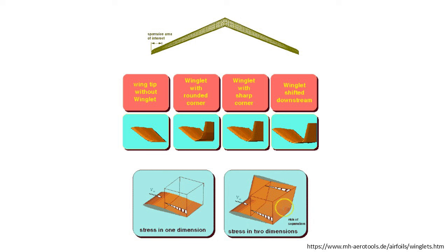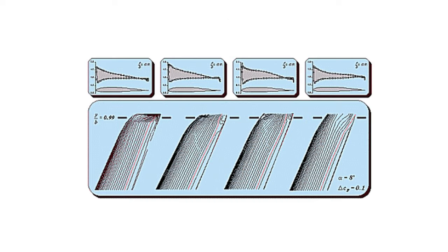Knowing this, you can see how a winglet, specifically a winglet with a sharp transition to the wing, could be an issue. Usually the wing airfoil only feels the pressure rise on the suction side in just one dimension, but with an effective winglet, another new spanwise pressure rise gets added to this in the winglet corner. The boundary layer pressure field in the region will have to overcome the sum of these 2 pressure rises, which naturally gives a higher risk of boundary layer separation. And we can minimize this effect by just blending the winglet into the wing with a wide, large radius blend to avoid a sharp corner.